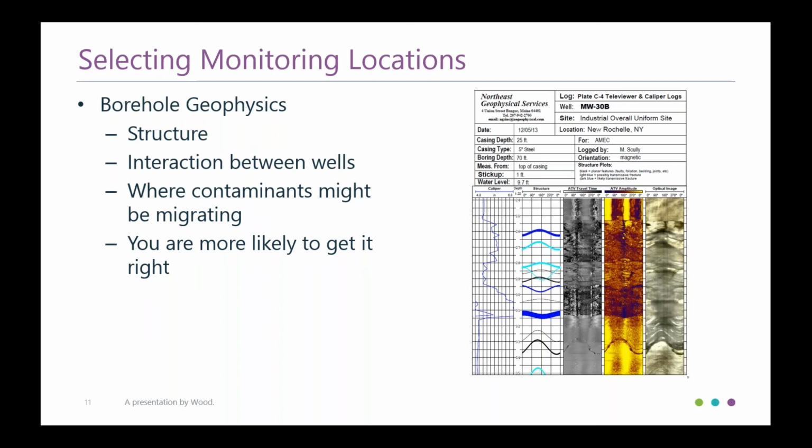I guess this doesn't work. Oh, so I think you can see the picture right there is that we're in a pretty good area for transmissivity for water, and that might be a good place to install a well. And if you do this on bedrock, you're more likely to get it right. You know, you're just guessing if you just go in blind and drill a hole and stick in a screen, unless you have some other information that might help you understand.